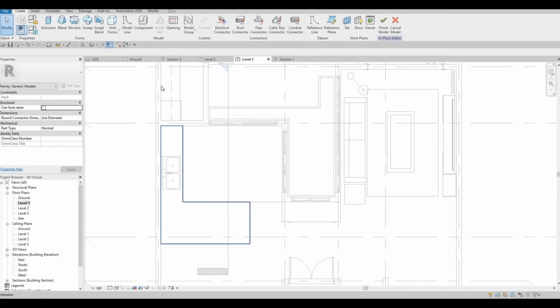The reason that we need to edit in place again on the specific one that we created before is because we are gonna void it. You can only do it on the void extrusion of that particular model in place, because if you keep on creating a model in place after a model in place, it will be very hard for you to void it, and it's not possible. So here I'm just going to do a void extrusion.